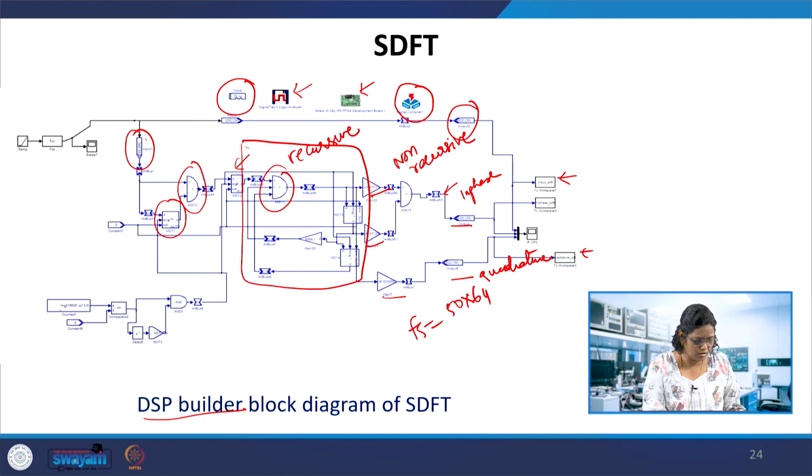And here is this mod counter. If you recall the digital part, when we designed the counters, you can now see the real application: ready-made blocks are available for the mod counter. We can fix the value which is required. So the 50 megahertz clock is divided to satisfy this FS, that is 50 into 64.